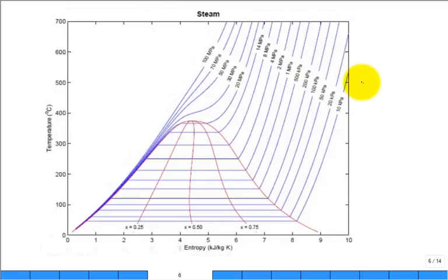So you come out of the boiler and you come into the first turbine. You've got to pick state 1 somewhere. All right, so let's pick it at 8 megapascal, and maybe not 600. Let's pick it at about 400 to 450, right in there, state 1. Why? Because I'm going to expand to an intermediate pressure after the first turbine stage. Where do I really want state 2 to land? Slightly in the dome, slightly in the dome.